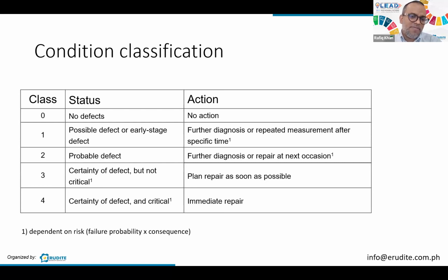It's maybe a bit difficult to repair cables with partial discharge, but you need to replace them. So you need to plan a replacement. Power cables can run for many kilometers. So which parts of the cable do you replace, or do you replace everything? This can give you a bit of insight.